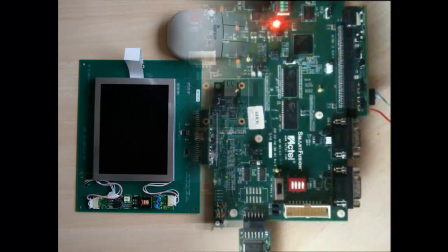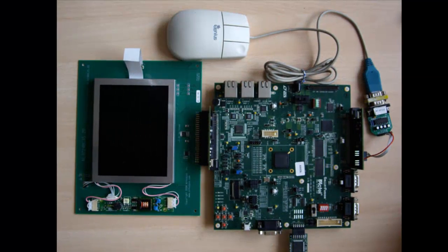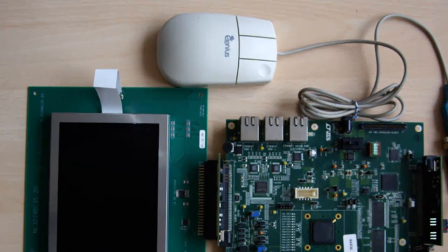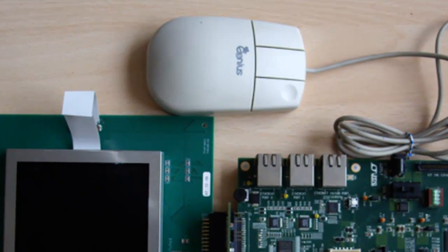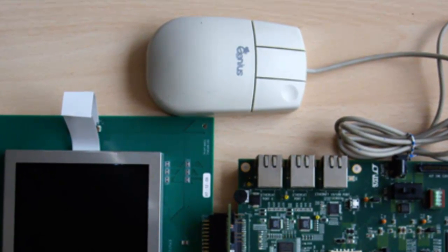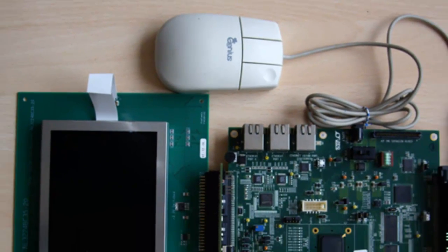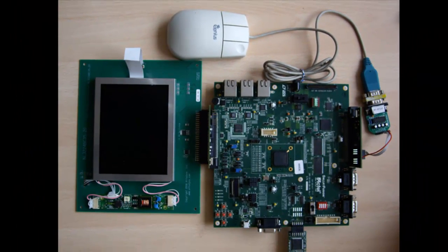When developing this demo, we also added support for serial mouse using a UART interface implemented using a soft IP UART block instantiated in the SmartFusion fabric. This mouse worked as a normal mouse would, but this requires a lot of setup and wires, so we decided not to show it in this video. The input device is probably not so critical for demonstration purposes, since real-life human interaction interface in all probability would be using a touchscreen or some service input buttons.